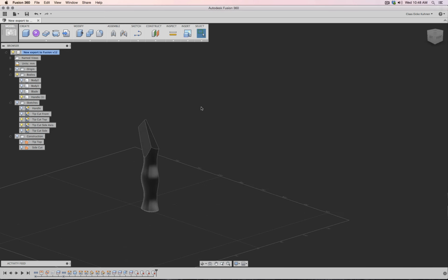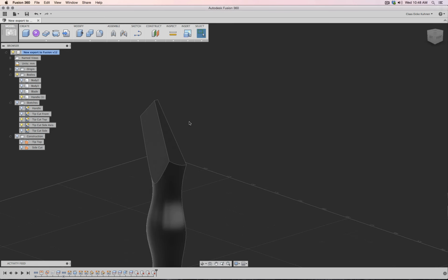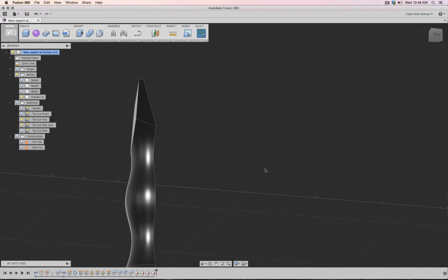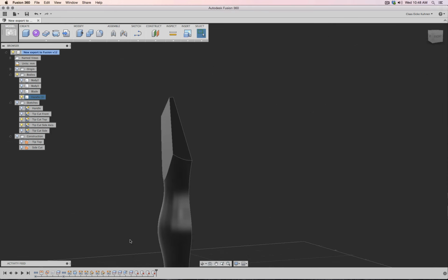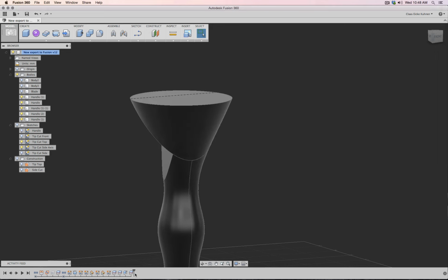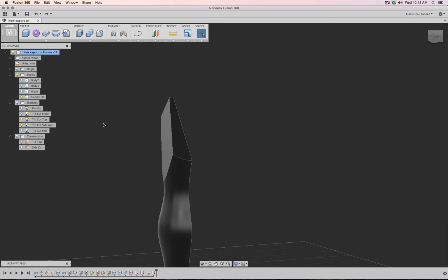Okay, so you see, similar situation. Instead of just splitting, I simply used the solid extrude command, and then for the extrude I used the subtract to remove it. Now, one thing maybe I would like to change is that this is being cut pretty straight. That doesn't look really good. So I would like to see how I could adjust that, so I only have a nice arc.